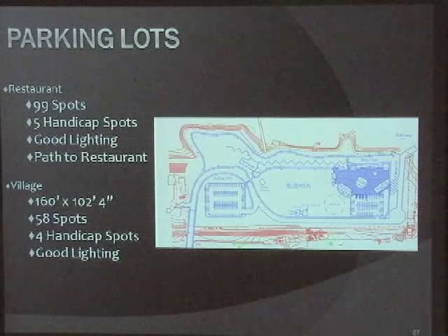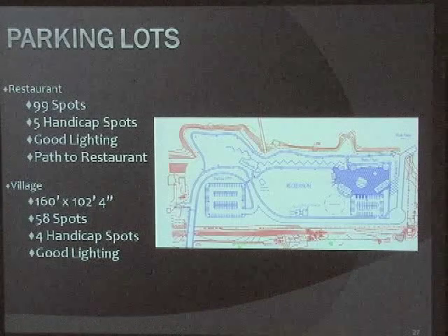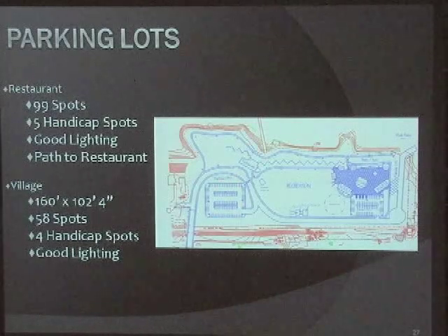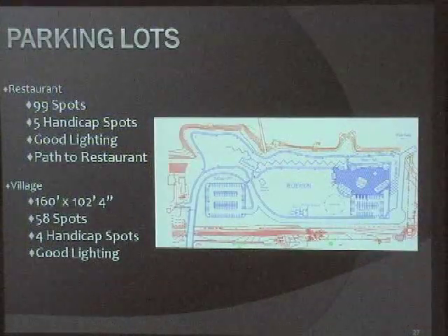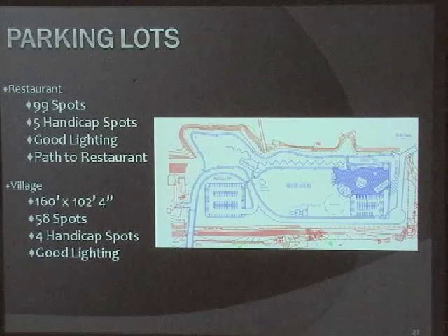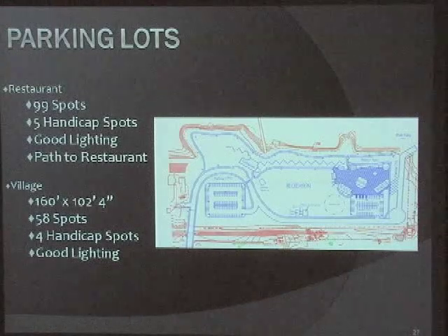So that equaled out to about 58 parking spots, which we over-designed for to 99 for hopefully if we put in other stuff later, such as fish markets or a marina. And then our village parking lot, for Tiverton municipal codes, we need 1 space for every 300 square feet of retail and 1.5 spaces for every residence, which came out to be 38 parking spots.